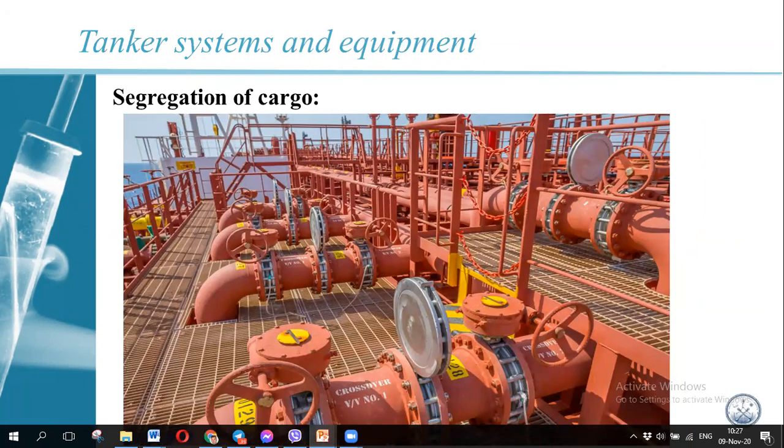This spectacle flange, you see here, here, here, everywhere, the spectacle flange. Here is a blank, and inside is the hole. If you remove these bolts, take the bolts off, and put this blind flange inside, here you will have a hole and the blind flange will be inside. So the cargo will never pass to this line, because this blind flange will be inside in the cargo pipe.